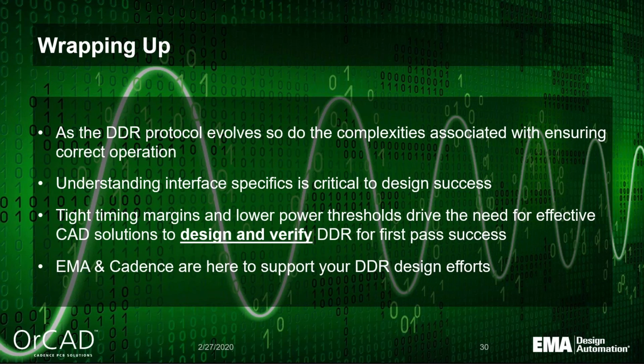Tight timing margins and lower power thresholds for noise to be present reduce the margin available for timing. So you have to go through very restrictive layout techniques, and then design and verify your DDR in simulation once you're done.